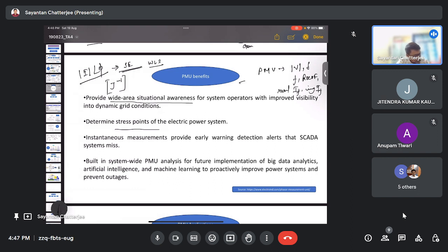if we consider the real and imaginary parts of the current, because in estimation we need to convert the measurements into their nonlinear function form as a representation of the state vectors, then if we measure the currents in this form, the Jacobian, the area, means the convexity of the Jacobian, changes. If we perform this inversion, then what we observe is that